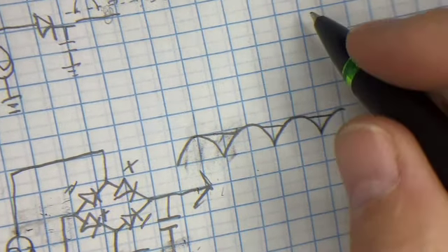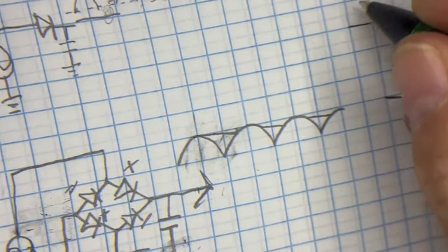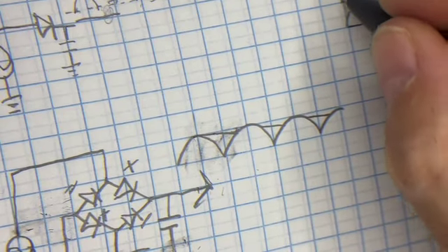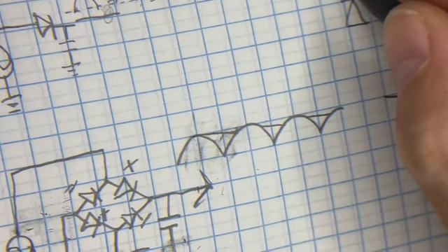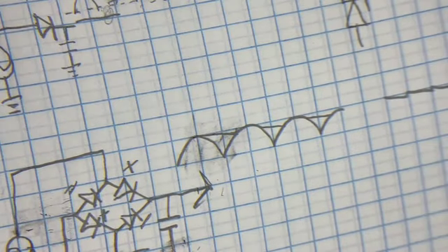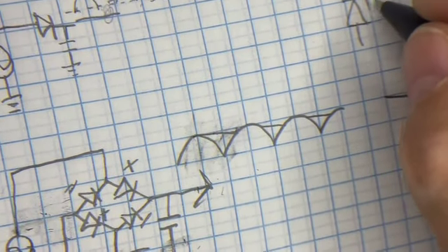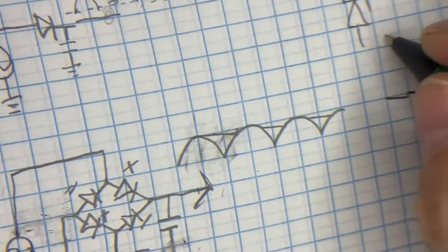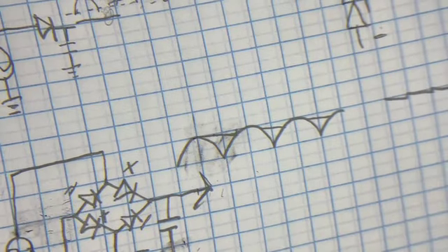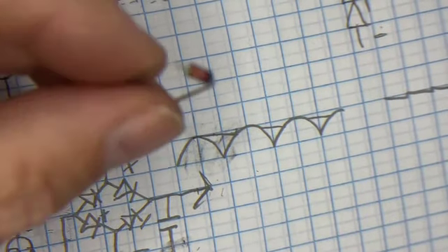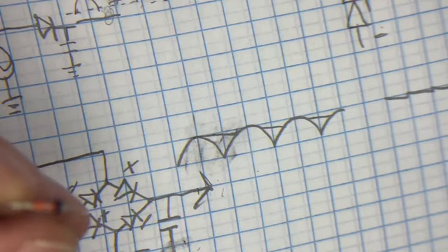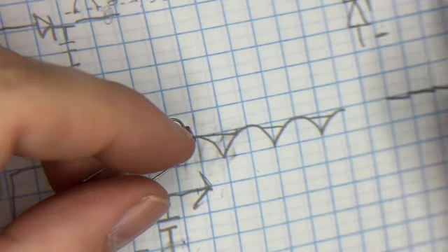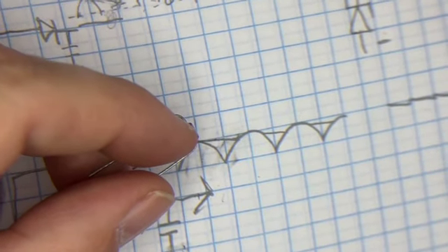The Zener diode is very similar to the typical diode, which has a symbol like this. The Zener will have these little marks on it like that. What's neat about the Zener is that they are put in reverse. That is, the cathode will go towards the positive and the anode will go towards the negative. Now, these guys are designed with a special purpose. It's something called the Zener voltage, or VZ.